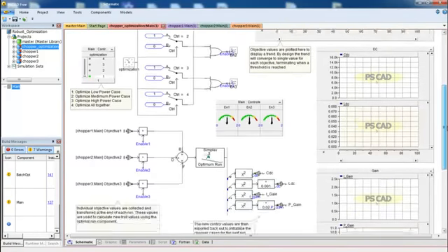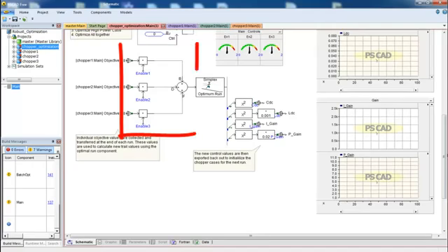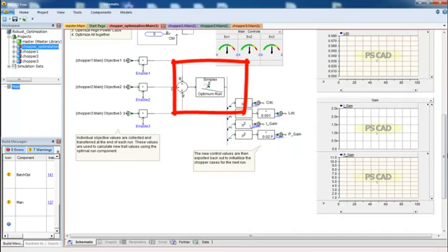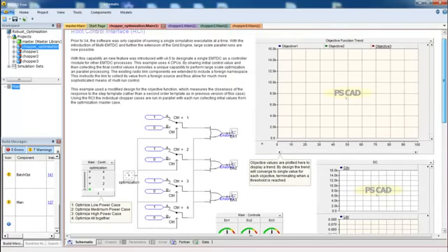The master project uses the objective values from each slave and then recalculates new initial parameters for each slave. This is essentially done with the PSCAD Optimum Run component. Now let's see how we set this up.